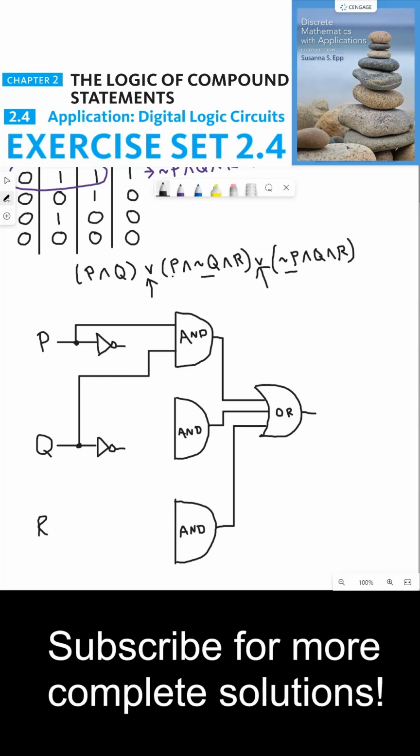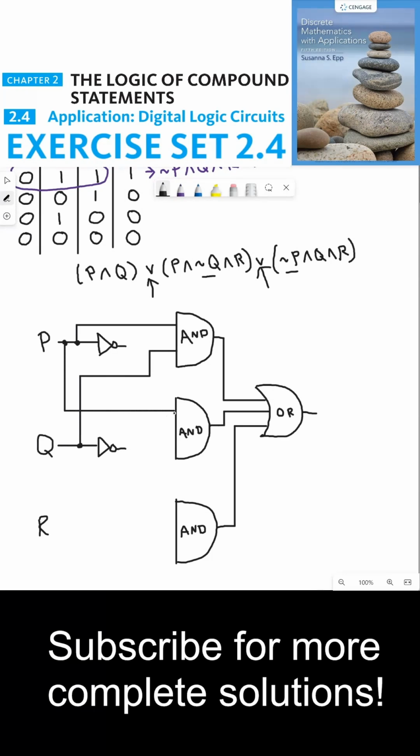The next AND gate, we need P and not Q and R. So I'm going to create another split right here from P and bring that input into this AND gate. So that's P. Next, I need not Q, which I have right here already built. And then I need the input from R. So that's the 3 inputs to my second AND gate.